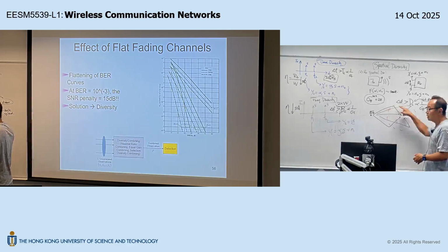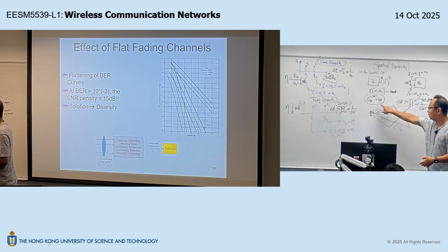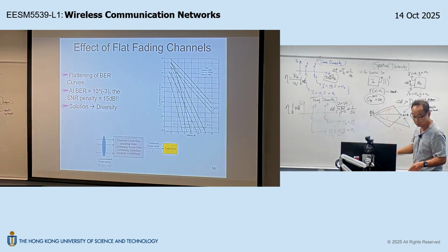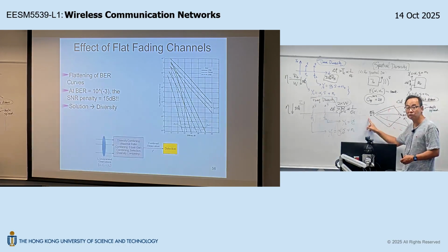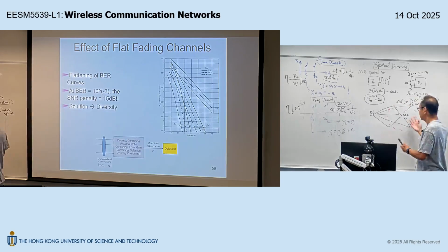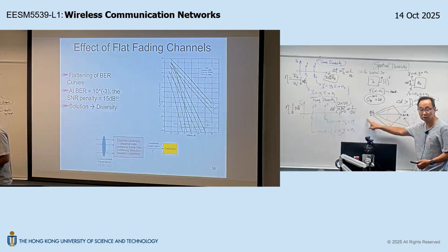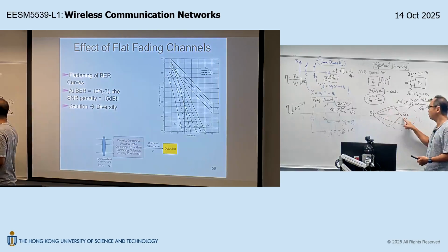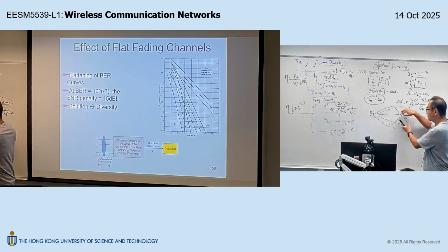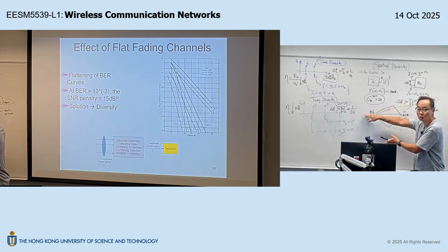Now, this is the downlink situation. The angle spread at the mobile is like 360 degrees. On the other hand, if you look at the uplink, if the base station becomes a receiver, then you just reverse the arrow. Signal from the mobile station is transmitted through these scattering clusters to the base station receiver.